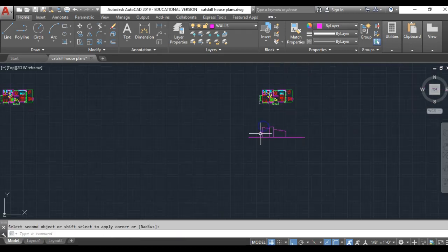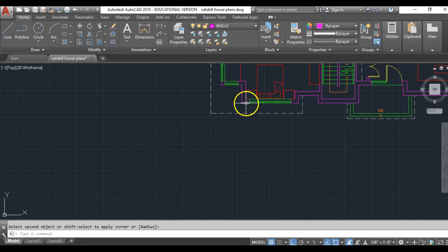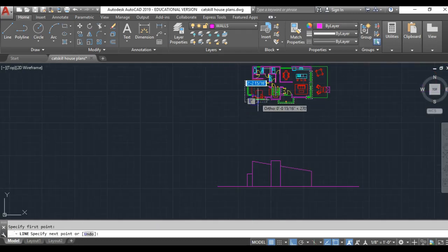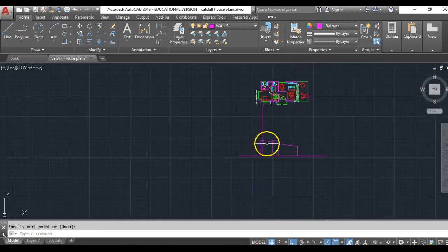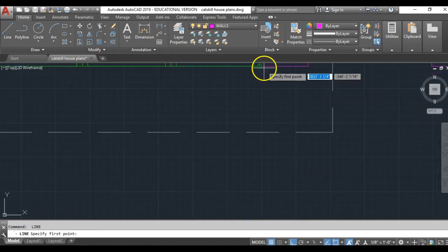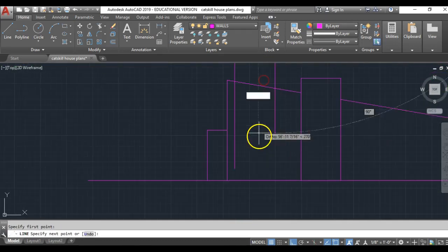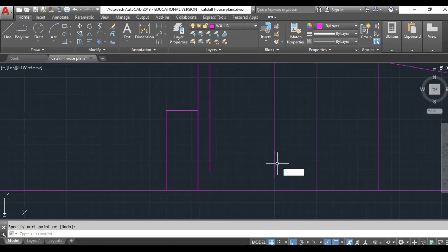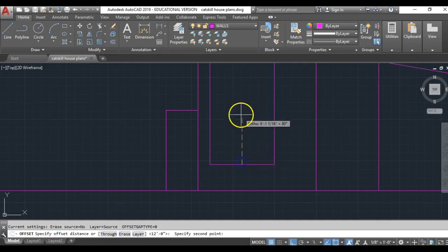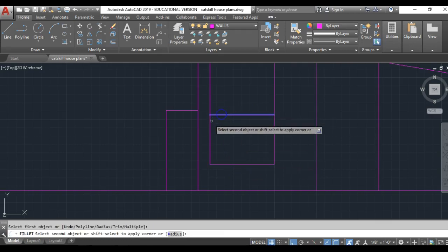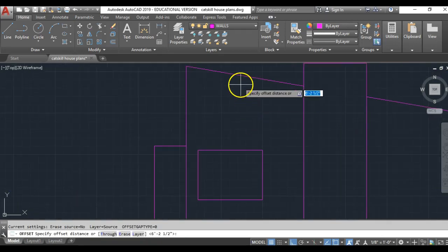Of course, the same can be done with windows. I can come down and draw some windows down here. This is all very basic stuff. Draw from the plan, draw down, draw across, and decide how high things are. I'm not focusing too much on dimensions in this video. Again, I want you to make those choices. I'm just trying to give you a heads up start of how to make elevations from plan.